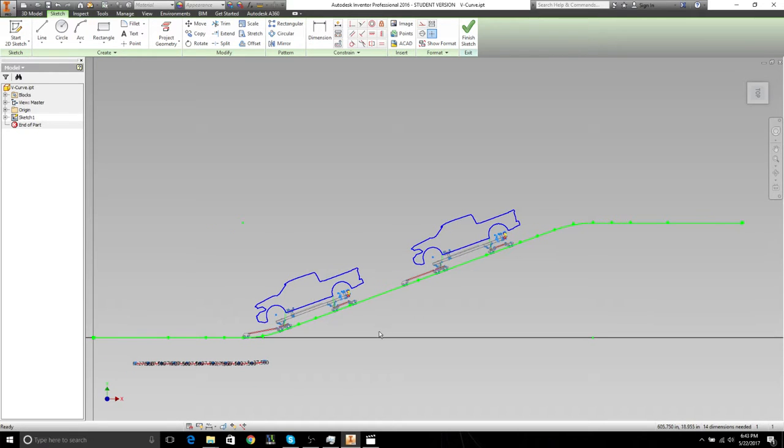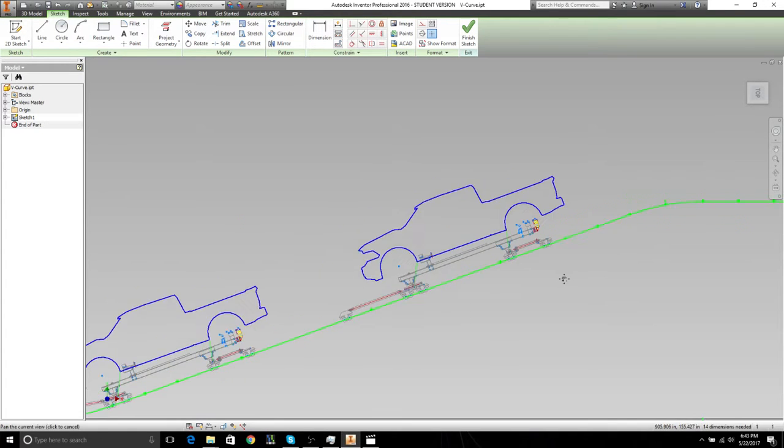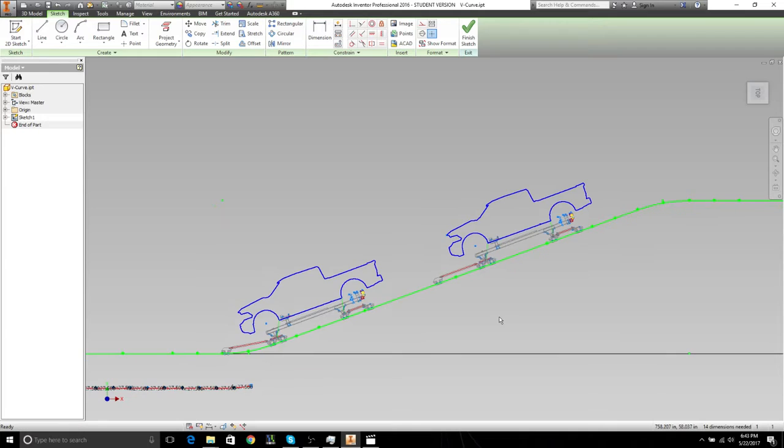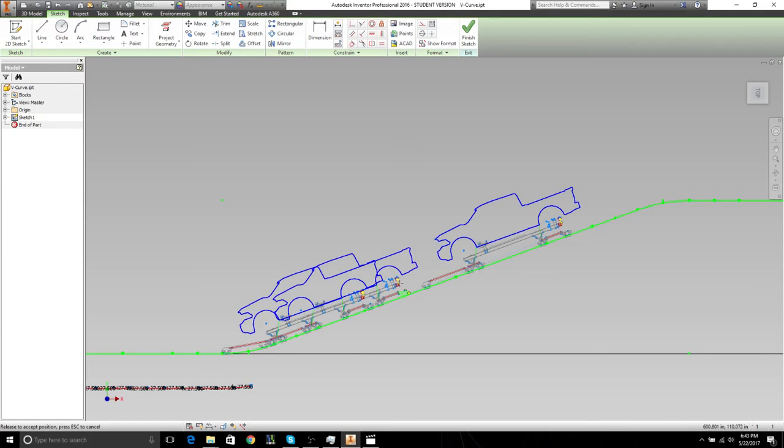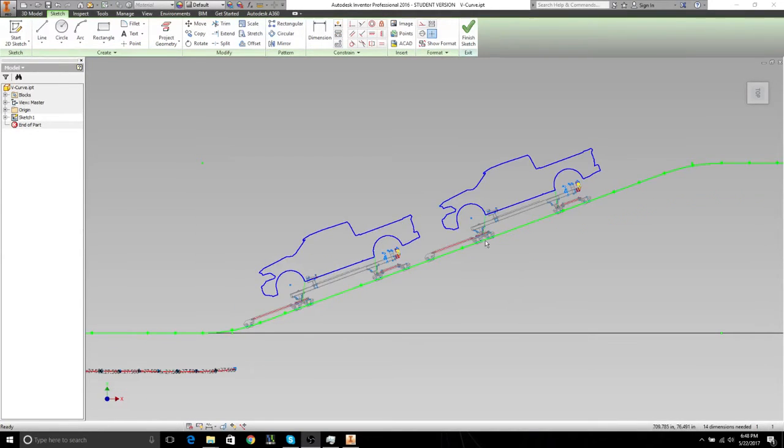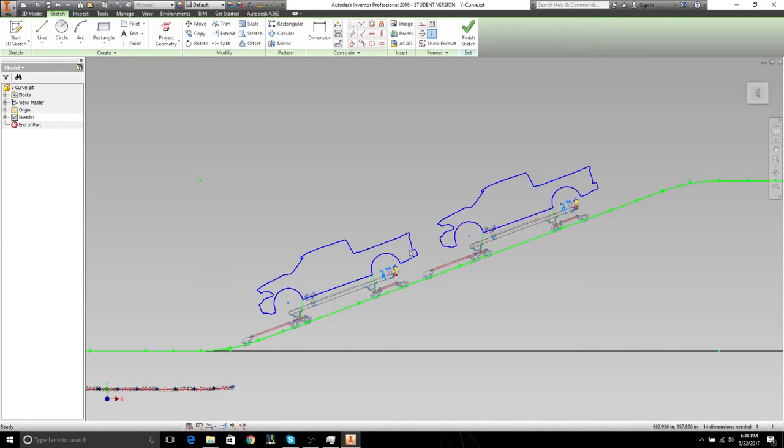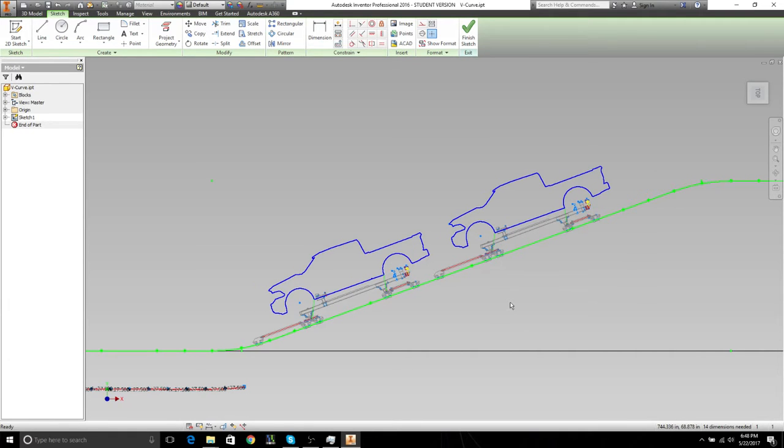So assuming you watched the video on how to set up these carriers and curves, you could have a situation like this. So right now what you see here is two carriers in the same sketch that can be moved independently. See, that one moves like that, and that one moves like that. So in a production study, it may become necessary to check for clearances between two products on two different carriers. So that's why these two different carriers are necessary to have in the same sketch.